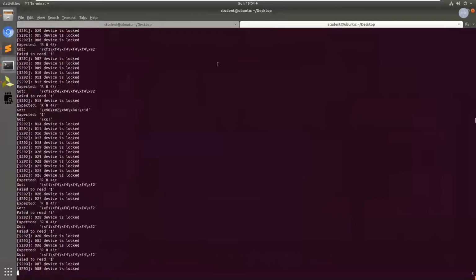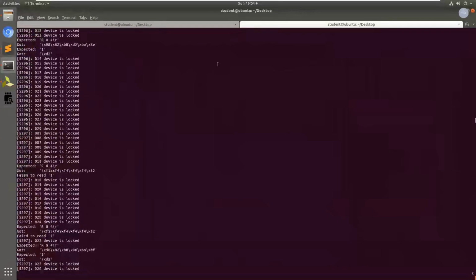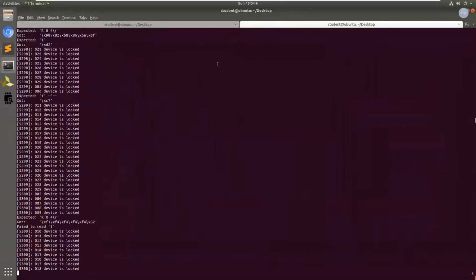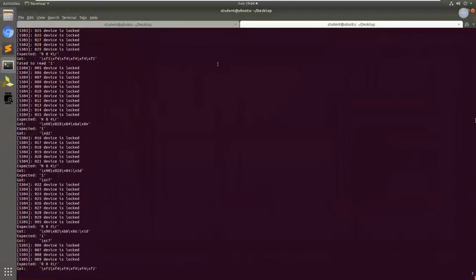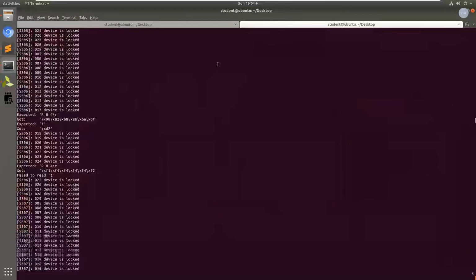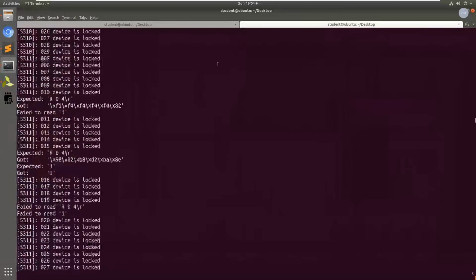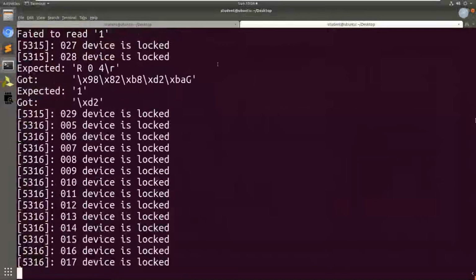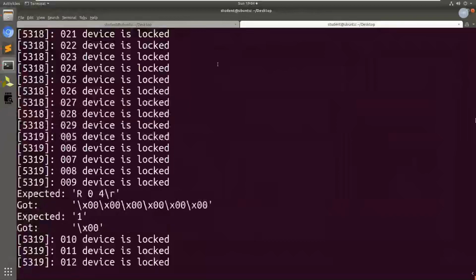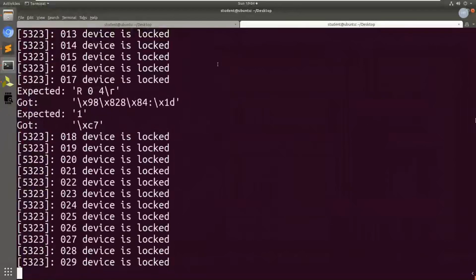So usually with this kind of board, the values where it will succeed to glitch the board will be about 5400, something like that. I mean, it depends on the voltage a little bit, but right around that value. Very rarely do you have to run it multiple times for it to actually output something or for it to actually crash. But essentially, you just let it run like this, and eventually it finds the correct position.